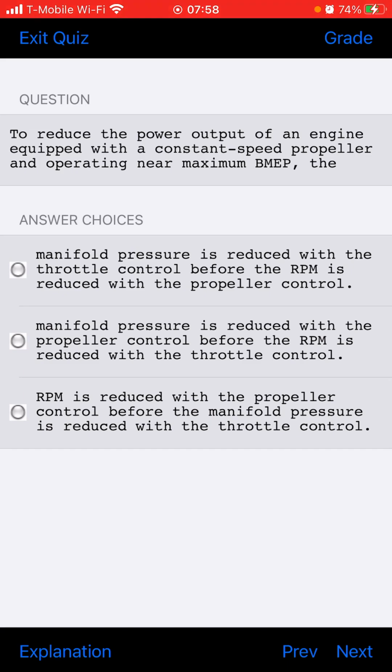How is the cylinder barrel inspected for out of roundness? Well, a cylinder bore gauge, telescopic gauge, and micrometer, or an inside micrometer, can be used to measure the top of the cylinder and also at the skirt. Two readings should be taken 90 degrees to each other.